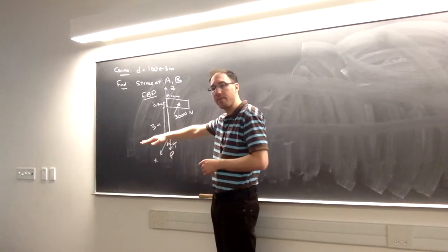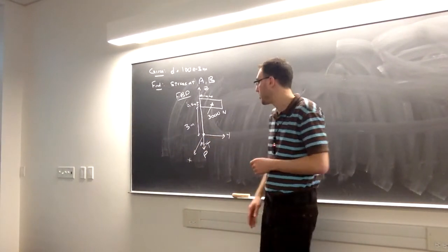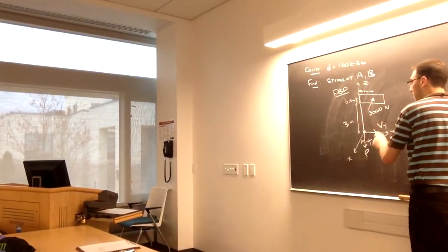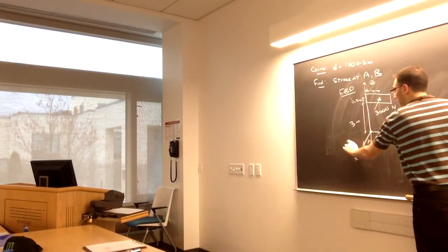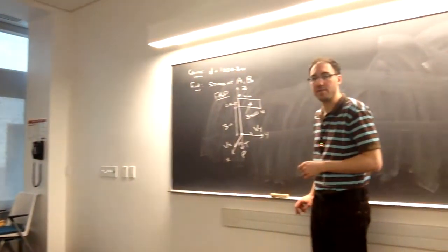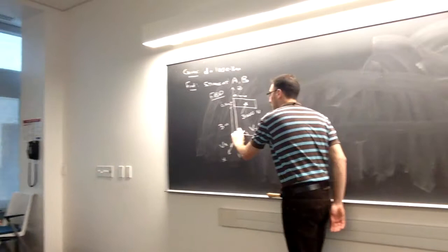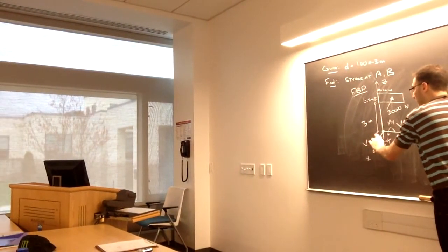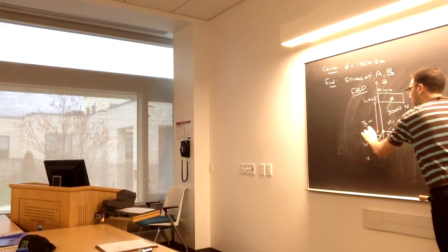Now in the plane of the cut, I'm going to have my components of the internal shear force. I'll have a Y component I'll call Vy, and an X component I'll call Vx. I'll assume they're both in the positive directions, X and Y. And then around the Y-axis, My, and around the X-axis, Mx.